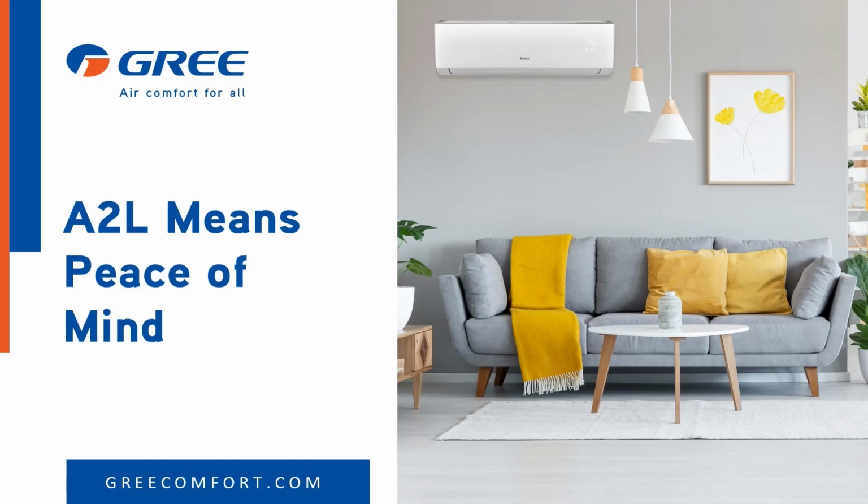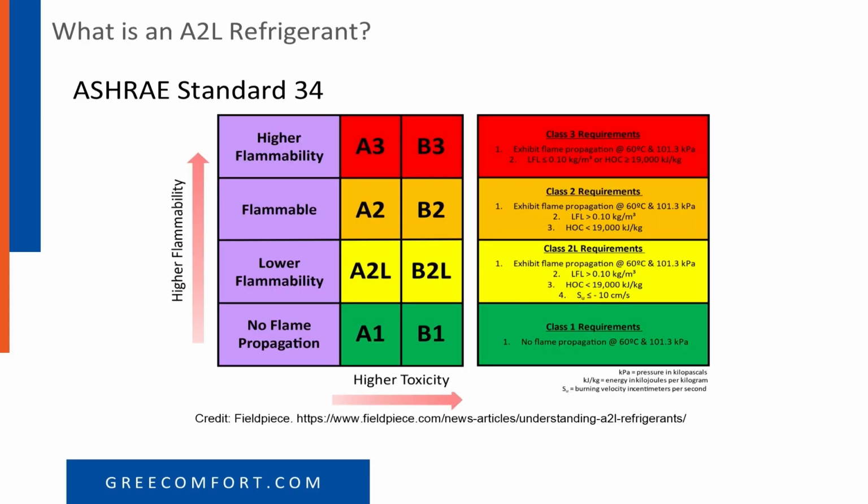So the first slide I'm going to talk about is what is an A2L refrigerant, or how are refrigerants classified? We'll look at the table showing ASHRAE Standard 34, and I'll address these things one at a time. At the beginning of these refrigerants, you have either an A or B. A refers to a low toxicity level, meaning if you breathe this refrigerant, it's not going to put you into shock and burn your lungs like mustard gas, anything like that. It is a low toxicity refrigerant. Then you have the B classified refrigerants, which are toxic, things like ammonia and others.